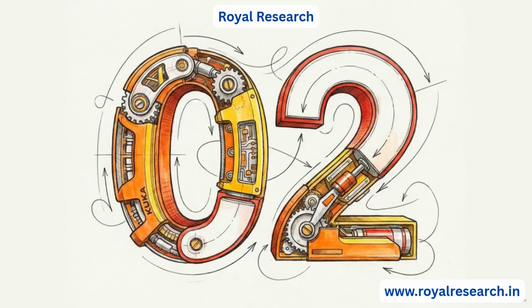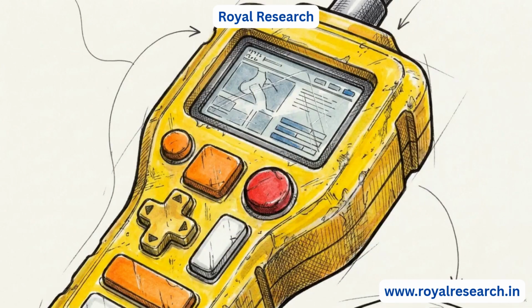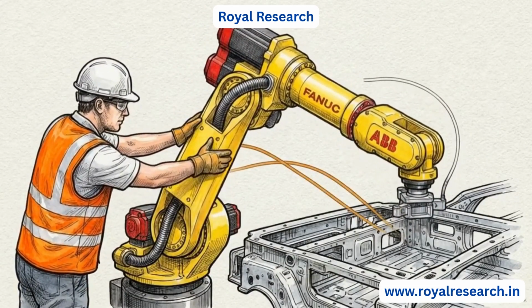This continuous digital testing environment naturally leads to the second pillar of the architecture, offline programming, or OLP. OLP is the execution and refinement of robotic code entirely outside the physical production facility. For decades, the industry standard relied on a device called a teach pendant. A human operator stands next to the machine, manually jogging the robot arm, recording coordinates one physical step at a time.